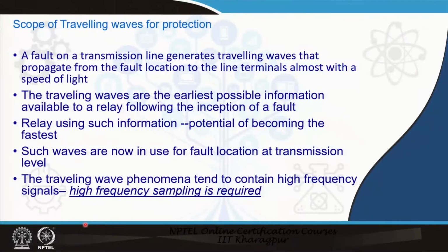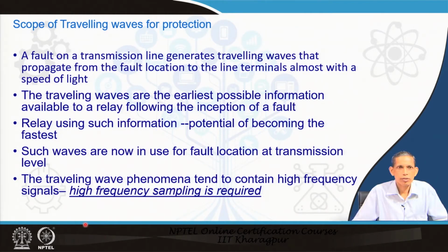Now, we have seen so many principles in earlier presentations and lectures based on the fundamental component, phasor value, and allied things like sequence components. So, we have mentioned that most of the available relays are based on sequence components, that is, the fundamental component or the phasor concepts. That is the 50 or 60 hertz component.